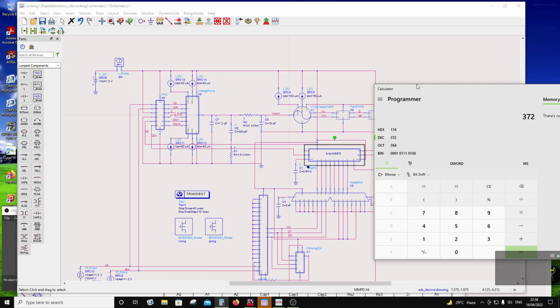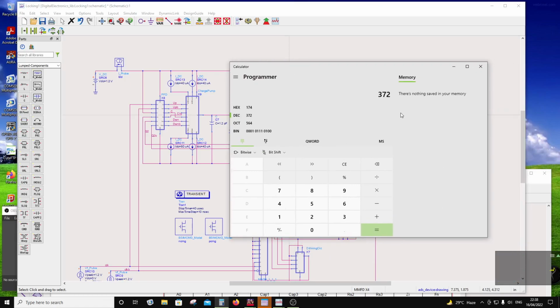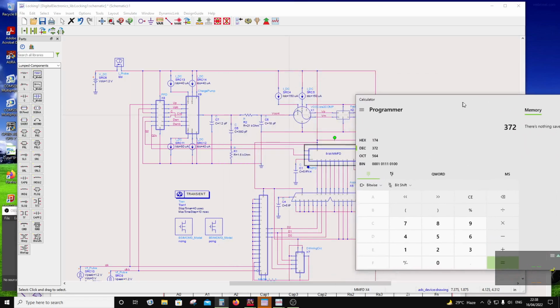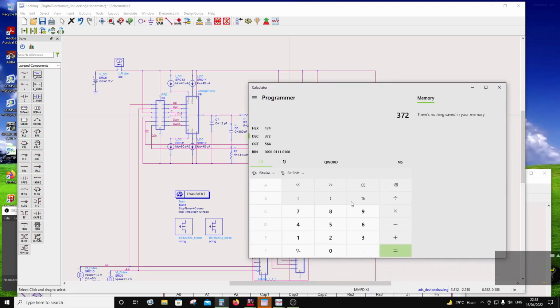Okay, another thing I forgot. 372 is not acceptable in your 8 bits. Now, how this works is, if it is an 8-bit multimodulus divider, then the minimum divide ratio is 256. So you can take 256 off of that. So you are left with 116.